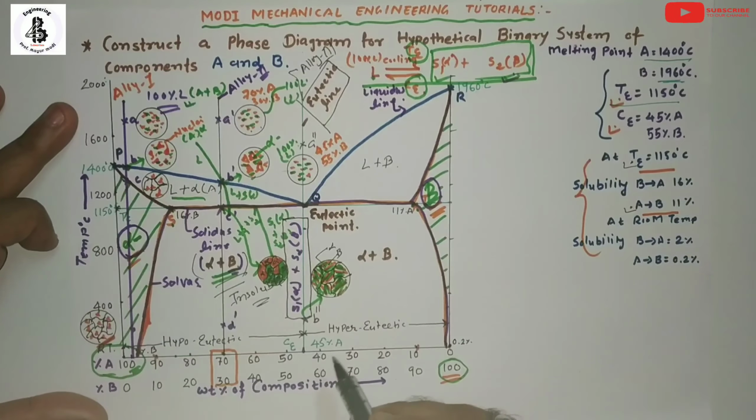So it will be the starting point of the solidification process. But here there will be an enrichment of the B metal. So it forms nuclei from the beta, because that will be the majority of the B metal which will be present for the hyper-eutectic transformations. So for making a microstructure at these points, you can see.